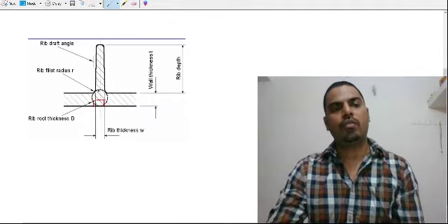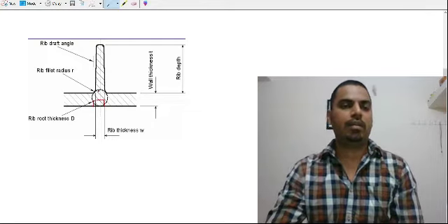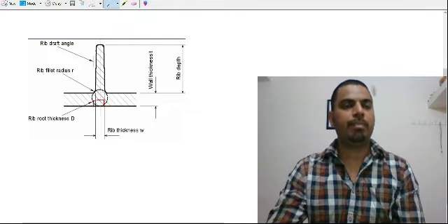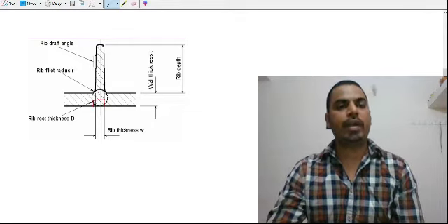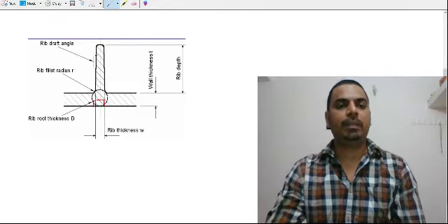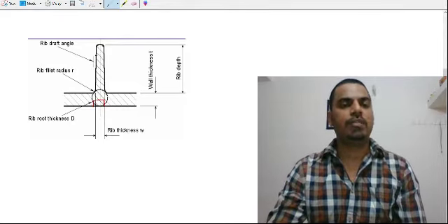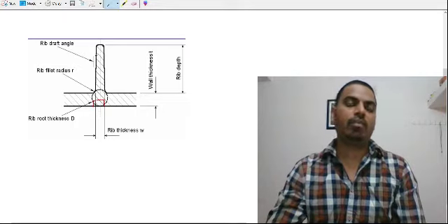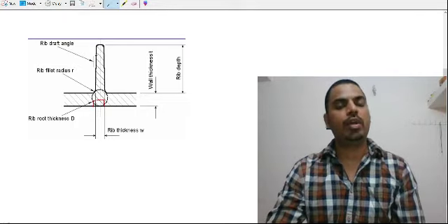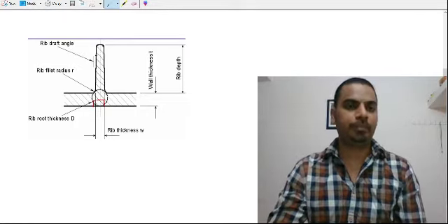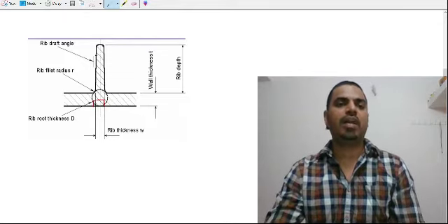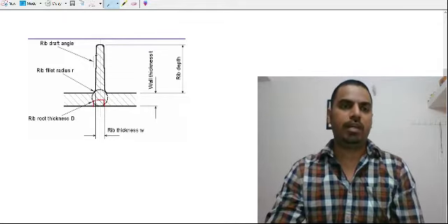Also we can go for a thin cross section rib, but for that we need to provide a rib which is deeper to have sufficient rigidity, and which will again cause failure of the rib due to buckling load. So we can't use a thinner rib.